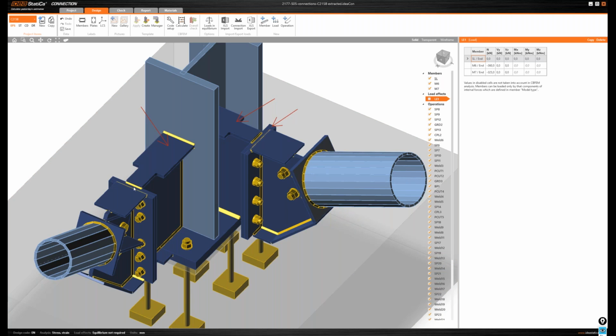We have two plates, two end plates, and a gusset is bolted on this end plate. The reason is that the diagonal with the gusset, all this part here, are removed later on, so that part of this connection remains in place and it is encased in concrete.